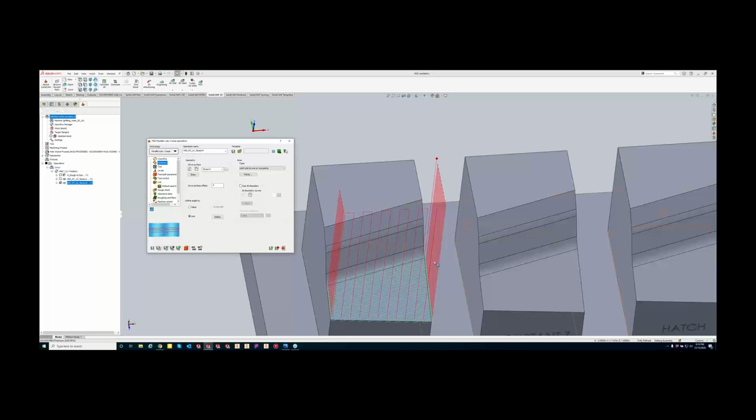So now if we do save and calculate, it eliminates all that higher degree angle of engagement. So what we could do is a constant Z for this upper half here, and then do our linear for more of this flat area right here.